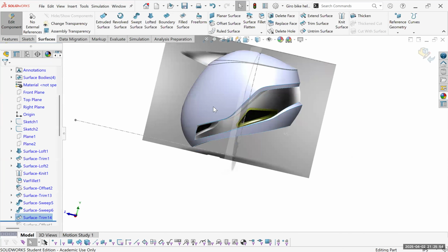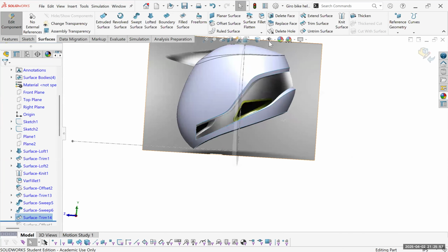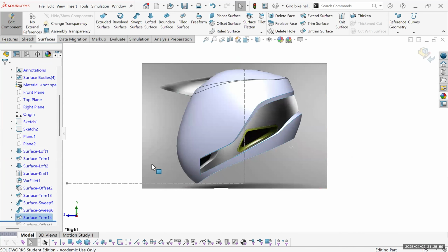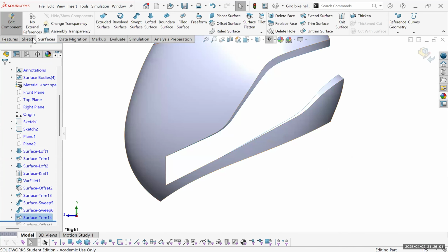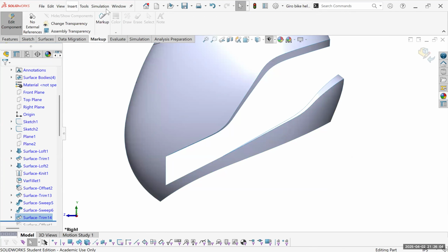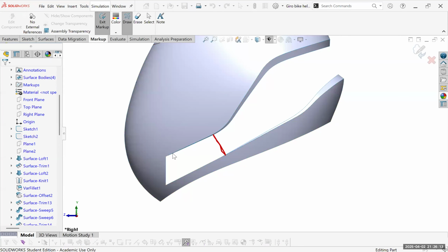So now, just gonna hide this. The goal is to get this really smooth surface here. I'm gonna mark up. We have the point kind of ending somewhere over here. So I'm gonna have to create a line and build this surface as one and make sure its curvature to the bottom, smooth to the bottom, is curvature continuous also to the side. The top would be contact because we still need that sharp crease.